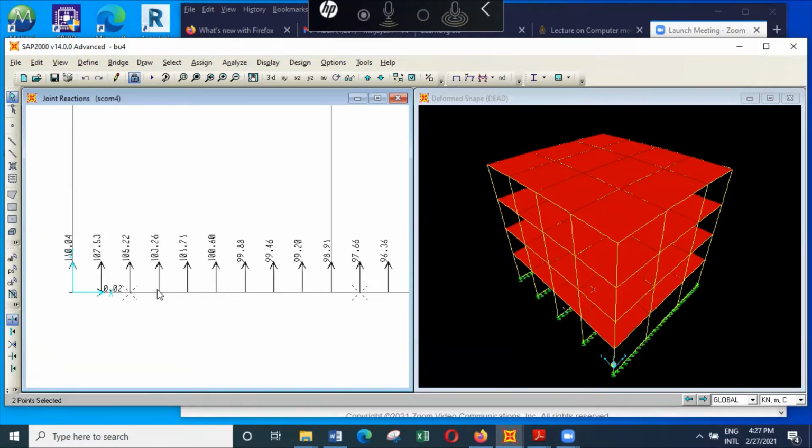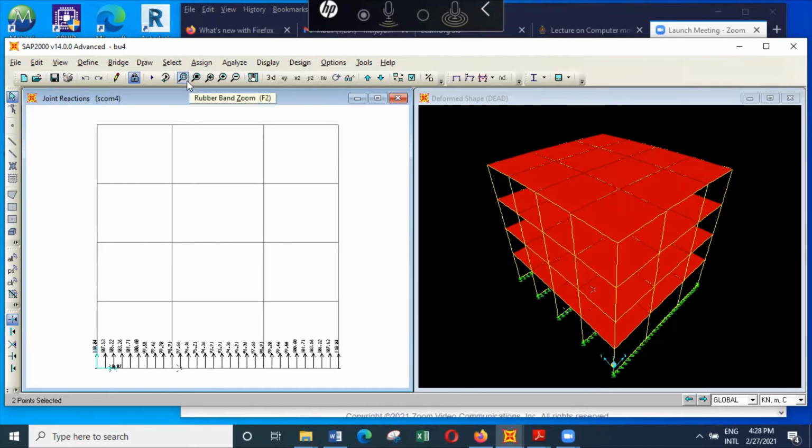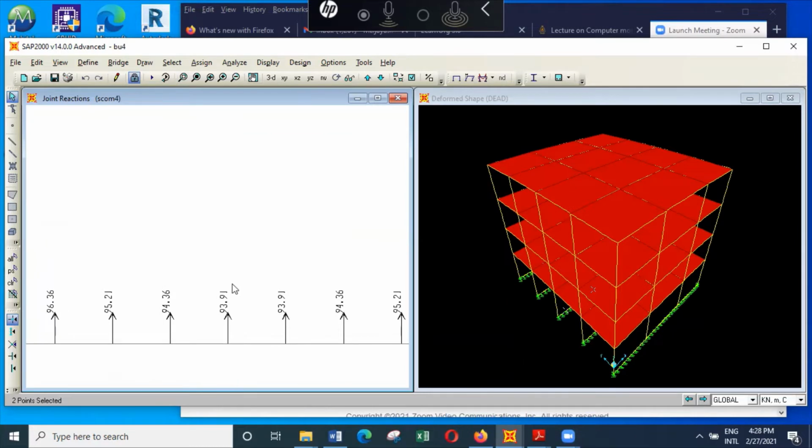But if you want, you can actually increase the width of the foundation to 1.9 meters, but for the time being, we'll stick with the 1.8 value. And in this area, you don't get a problem, and in the middle of it, you don't have a problem.